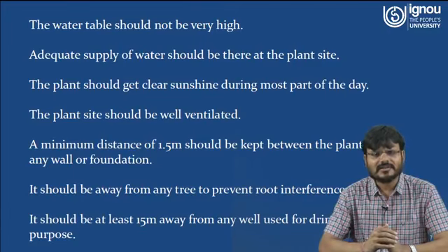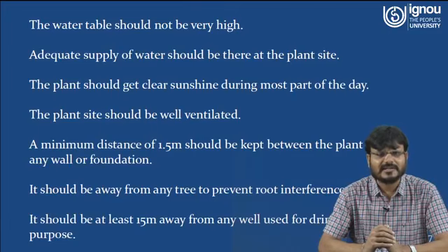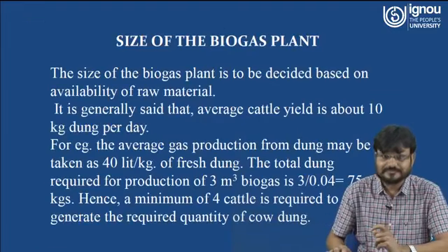Another point to remember is that the plant site should be well ventilated. A minimum distance of 1.5 meters should be kept between the plant and any wall of the foundation. It should be at least 15 meters away from any well used for drinking water purposes.